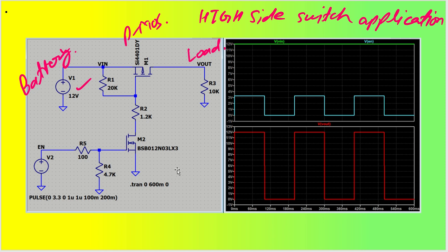always. So let us say you are going to use one MOSFET here, an N channel MOSFET, and this is my drain, this is my gate, this is my source. Now your microcontroller can send an enable signal here. I am going to put a pulse wave here for simplicity. So this is my MCU GPIO, or some enable signal which will be enabling this.